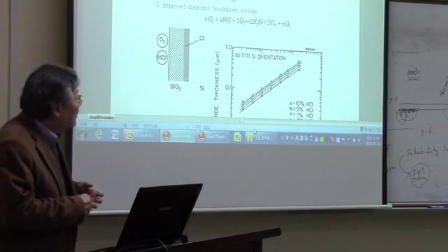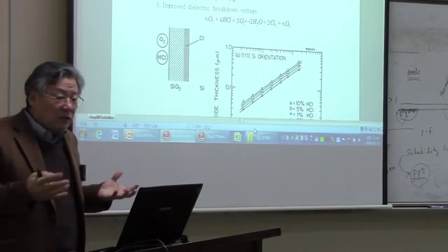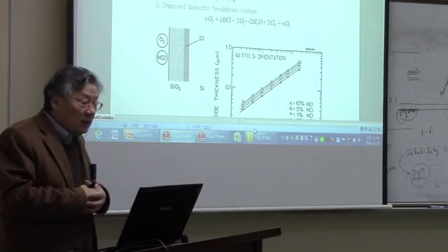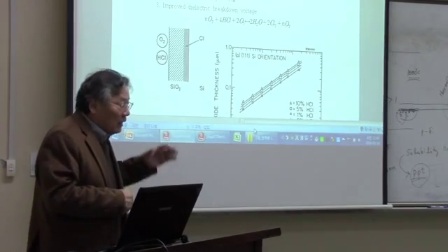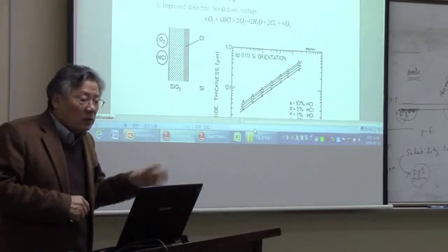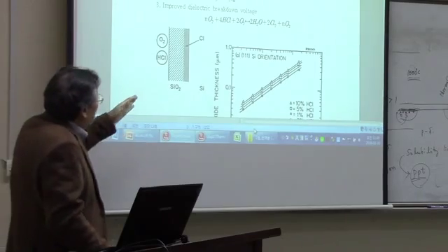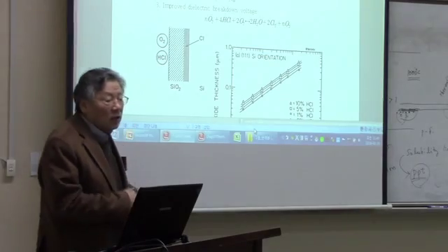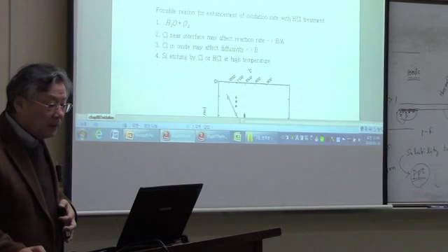Not only does it enhance the growth rate, because the dry oxygen is going to form water like a wet oxidation, but it can also annihilate and decrease the number of fixed charges, and correspondingly the interface trap charges, where the Cl minus ions accumulate at the silicon oxide interface. That's beautiful, isn't it? Okay.